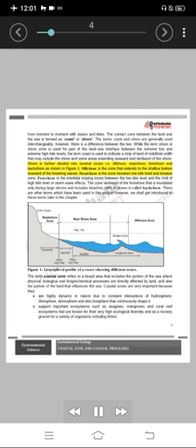Shore is further divided into several zones, i.e. offshore, nearshore, foreshore and backshore as shown in Figure 1. Offshore is the zone that extends to the shallow bottom seaward of the breaking waves. Nearshore is the zone between low tide level and breaker zone. Foreshore is the intertidal sloping zone between the low tide level and the limit of high tide level or storm wave effects. The zone landward of the foreshore that is inundated only during large storms and includes beaches, cliffs or dunes is called backshore. There are other terms which have been used in this section, however, we shall get introduced to these terms later in the chapter. Figure 1. Generalized profile of a coast showing different zones.